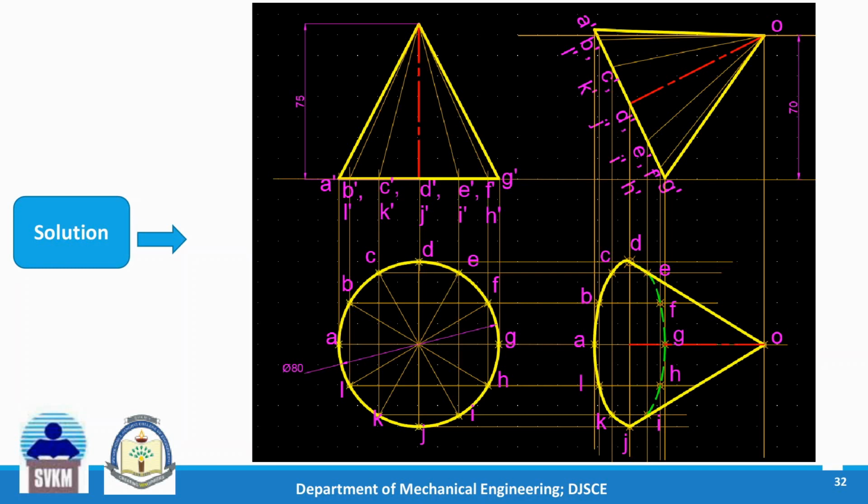We'll draw one locus, and from this point we'll take this distance and cut on that, and then reconstruct this figure here. Take the projections down. Take the horizontal projections. Take these projections down and take horizontal projections from the first step, and at the points of intersection, name them properly and join the points as you are seeing from the top. So whatever is visible is shown with object line, and the hidden portion is shown with a dotted line, and then the axis is also shown.